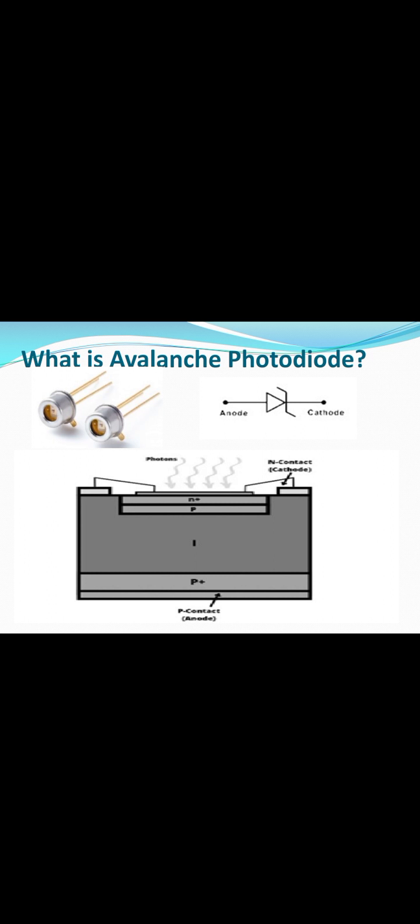The gain normally decreases as the temperature rises. This is because at higher temperature the free path between collisions is small, and many carriers do not get a chance to reach the required velocities for producing secondary carriers. Temperature compensation is used for the APD, as it is needed over the expanded temperature range. This is the working of the avalanche photodiode.